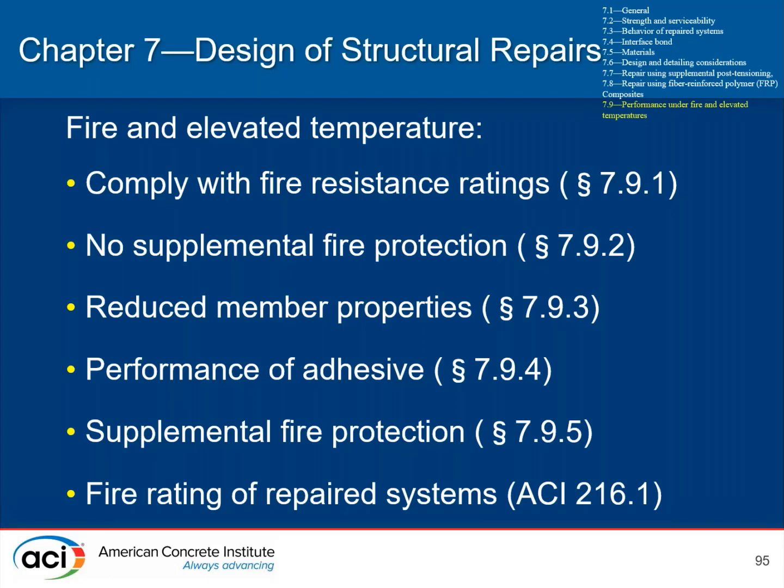The reduced member properties are accounted for in Section 7.9.3. And in addition to the performance of adhesives, any potential supplemental fire protection and the requirement of the fire rating of the repaired systems in compliance with ACI 216.1. And so Section 7.9 details the requirements of the code with regards to compliance in this respect.